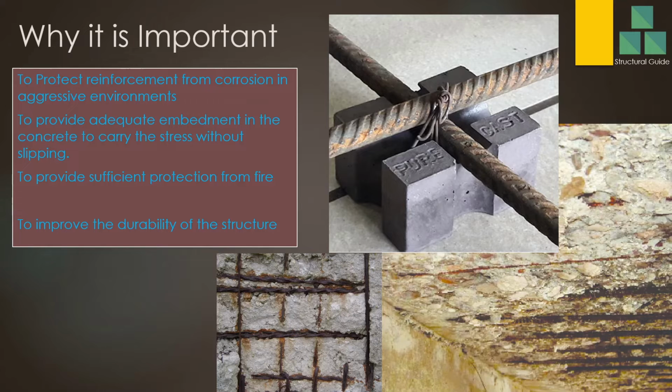In a structural element, the concrete and the steel are the main components that carry the stresses. Tensile stresses are carried by the tension reinforcement, so we need to protect the reinforcement. If they corrode, there will be issues. Carbonation attack, chloride issues, and sulfate issues are some of the chemicals that affect and cause the corrosion of reinforcement.